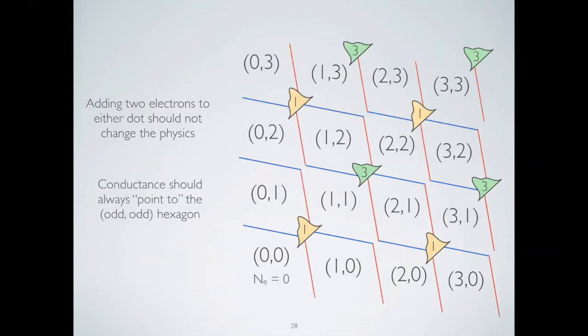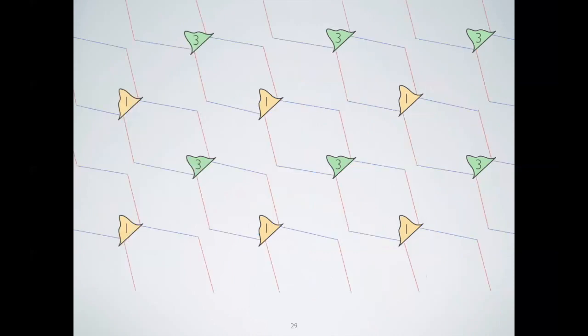If we map out this space and focus on the lines between the triple points, specifically the ones that have 1 extra electron, not 2, you'd expect a picture like this, where you have higher conductance right next to where you have 2 electrons on the double site, and lower conductance where you have 0.